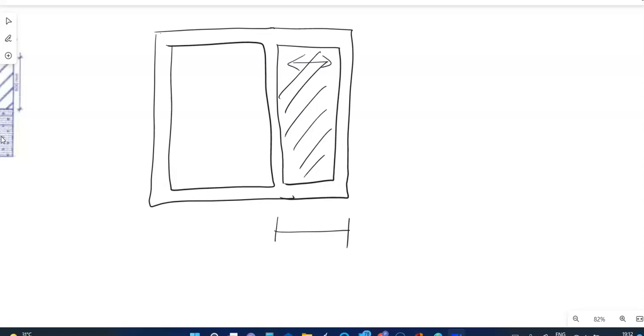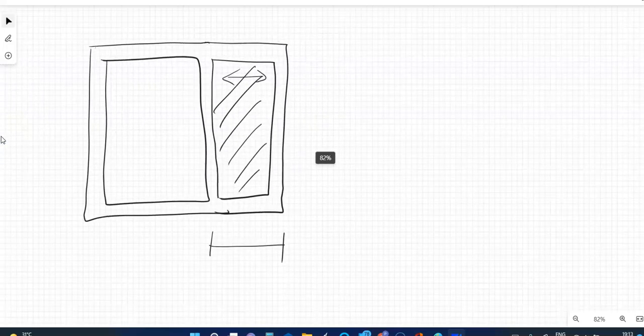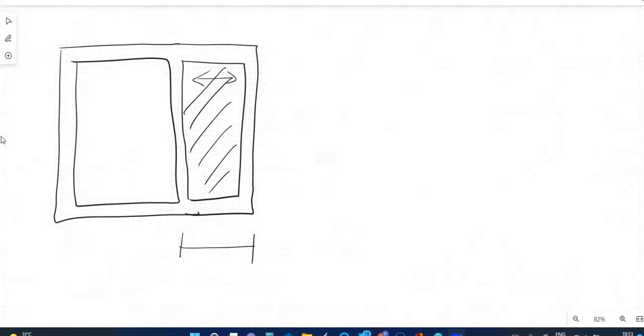So now if you treat this as a completely discontinuous slab, this is a simply supported condition and you will end up with a moment of WL square by 8. Since it's a one-way slab, it is going to span in one direction and your moment is simply WL square by 8. The question is, is it okay to design like this?